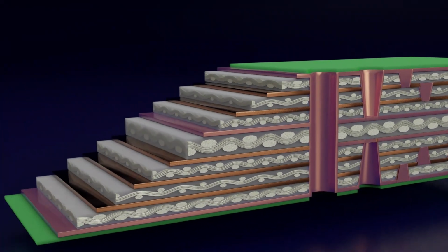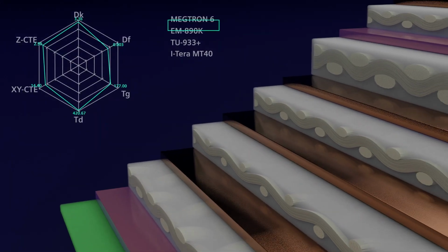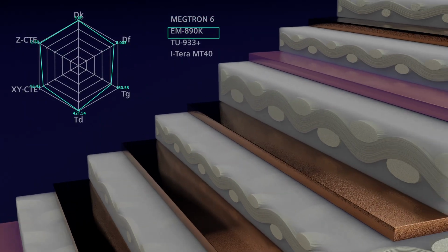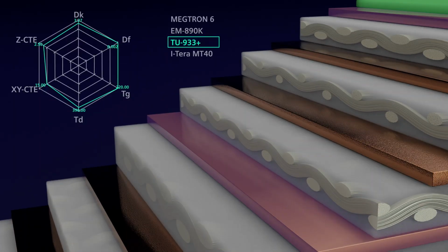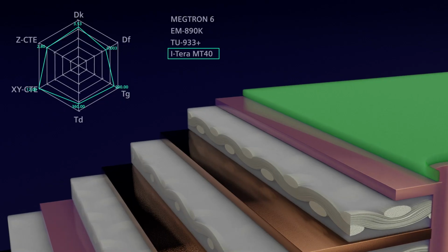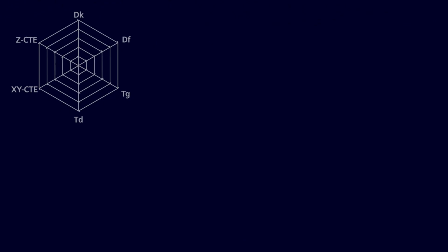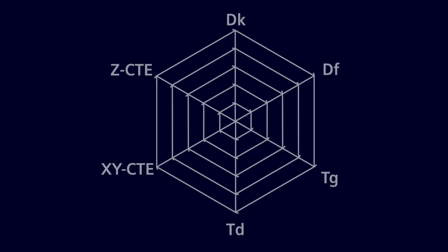Gone are the days of specifying FR4 and being done with it. There are now dozens of laminates available in dozens of configurations. Punting this decision to your fabricators was fine 5 years ago, but if you are working on high-speed boards and using multiple fabricators, you are going to have to start getting serious about your stackup design.